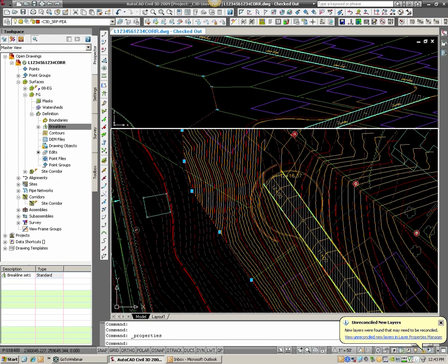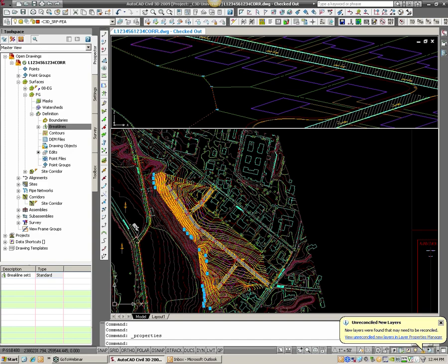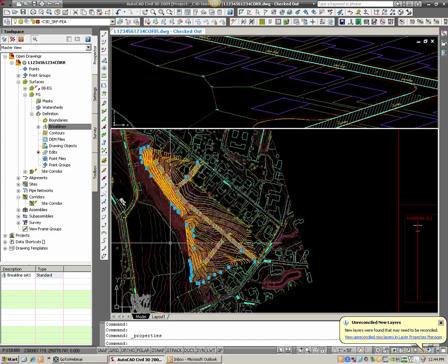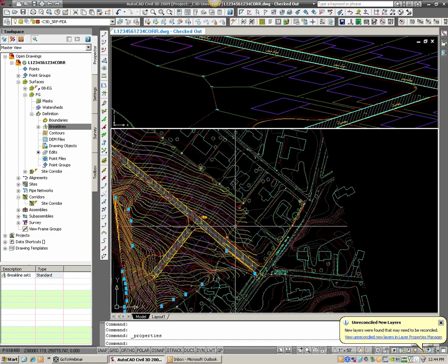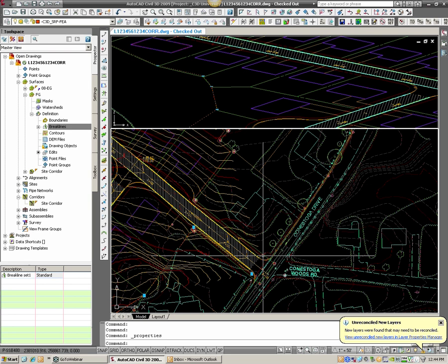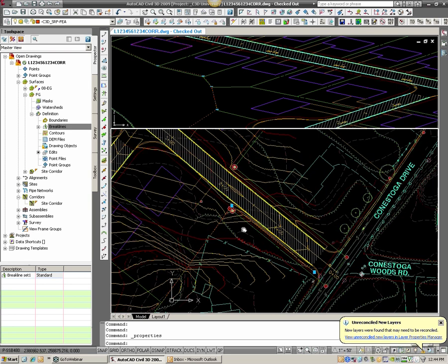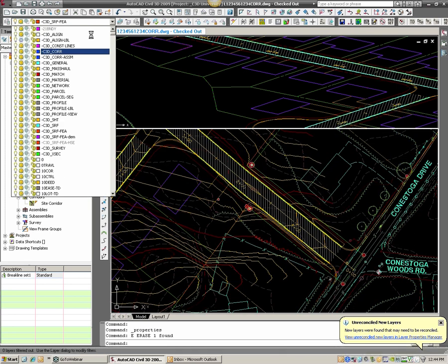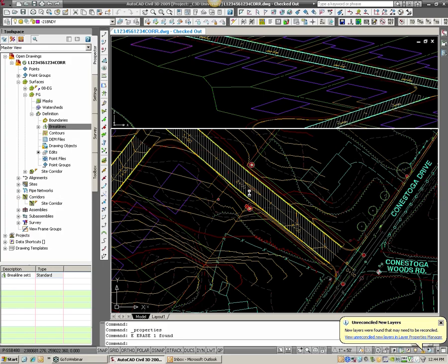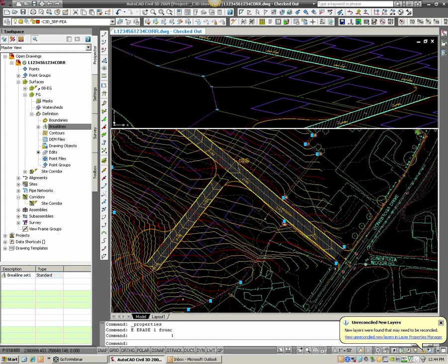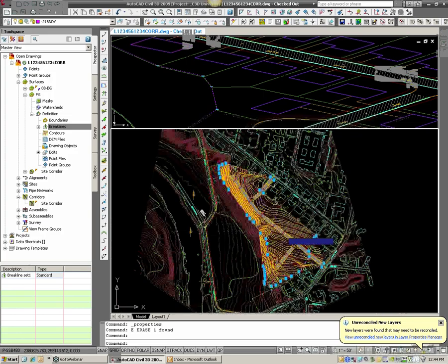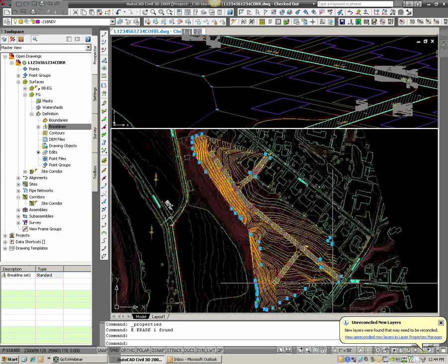Well, now that this is a polyline, I can actually use this for my boundary. So I would do the same thing. There's actually 2 segments. There's a segment down here. It's pretty long. And then there was another segment on the high side, and I'd have to draw a polyline across to connect them all together. And what I would ultimately get is this boundary. So I can click that. Hopefully you can see that. At least the vertices. This is a boundary. Put it on my 21 boundary layer. It goes all the way around the site.